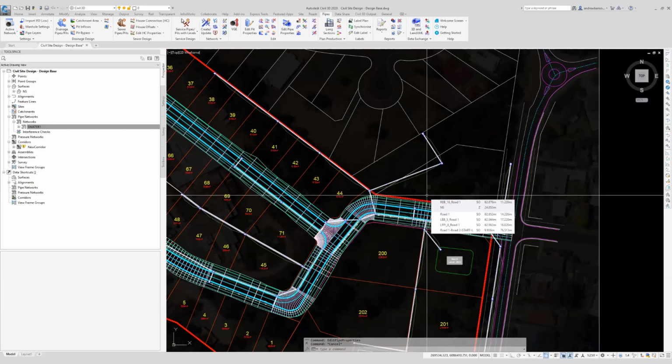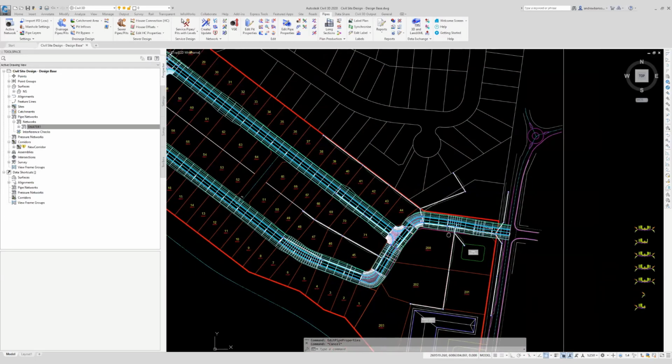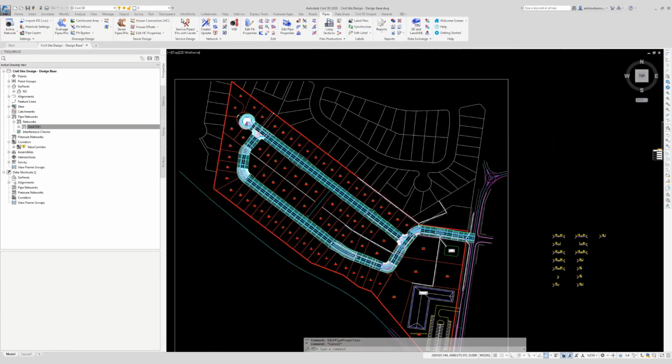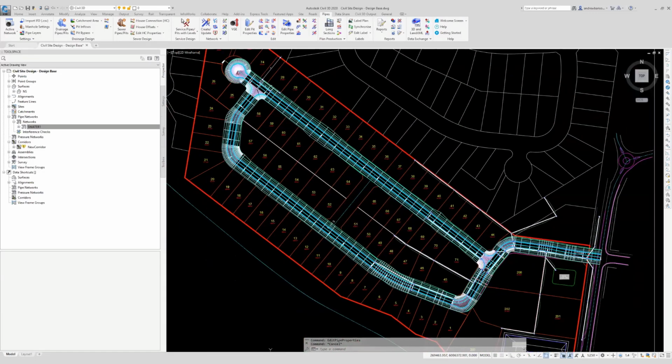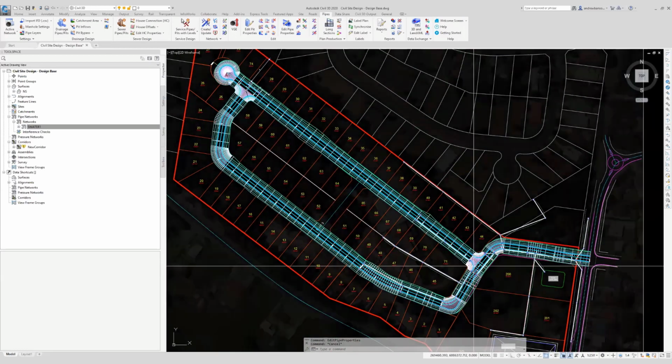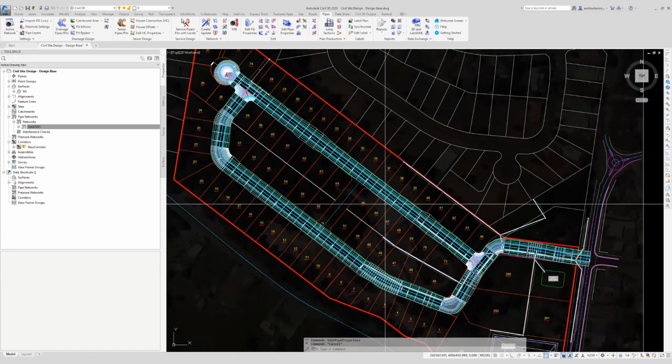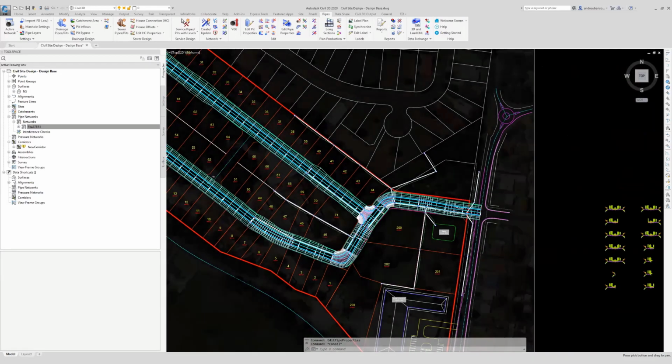For example, there's an add-in program called Trimble Link, which some of you might have, you might use for construction set out. It directly takes a corridor. If you have the corridor, you can use Trimble Link then for set out. So there's a lot of advantages for being able to produce the corridor. The issue in the past with the corridor has often been the process of building one with intersections and cul-de-sacs and that. So it can be done. It's just a lot more work involved.